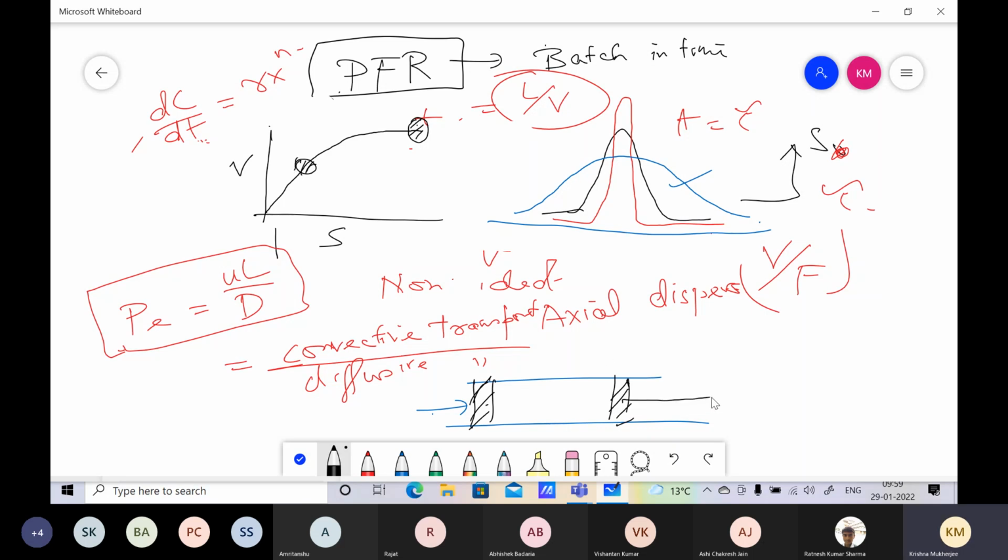So for the fact that this particle resides for very long time, now these particles, this is T, so these particles here are residing for much longer than average, but their extra conversion rates are much lesser because now the reaction rates are very low here. But these fellows who were getting converted at these values are now not getting enough time. They will also go out.